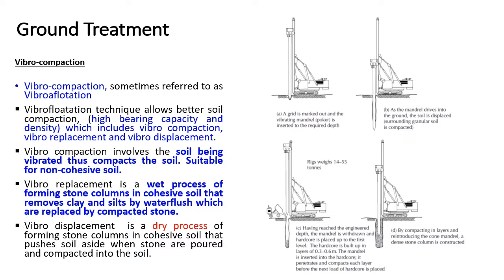Soft soil, man-made, or other strata can be reinforced to achieve improved specification requirements, while slopes can be treated to limit the risk of slip failure. The allowable ground-bearing capacity for low to medium-rise building and industrial developments is in the region of 100 to 200 kN per meter square. Beneath tanks on embankments or slopes, 100 kN per meter square can also be achieved. Ground condition may allow heavier loads to be supported.